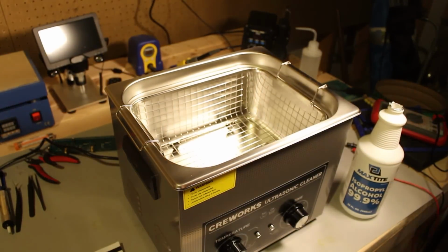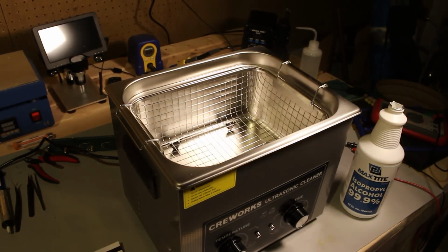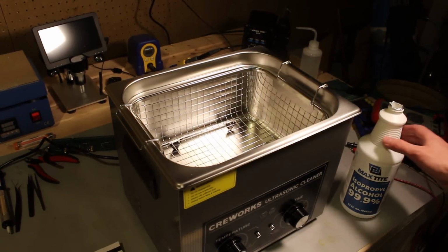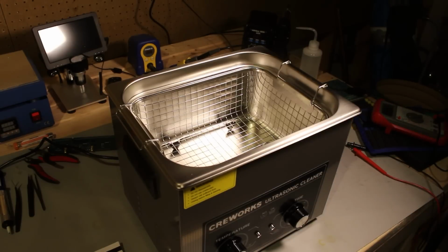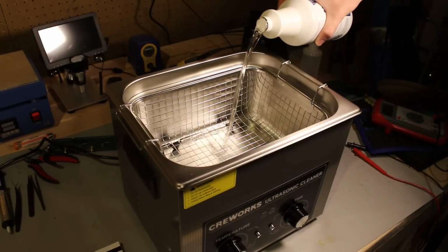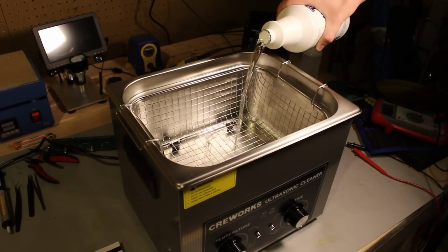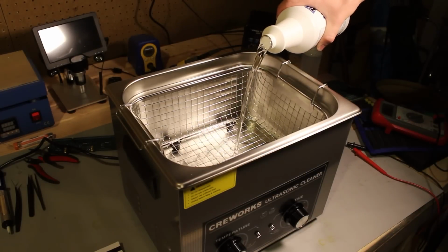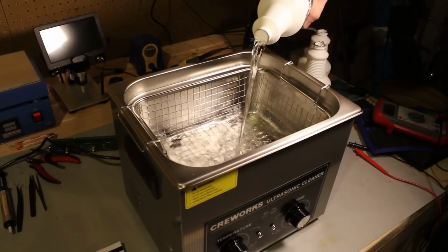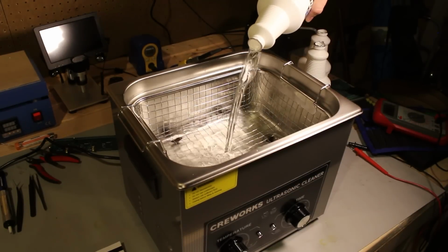You can use a brush to clean everything off, but luckily I got this cool new toy to play with. Introducing the ultrasonic bath. It works by passing high-frequency sound waves through the bath, creating tiny bubbles which then collapse and remove contaminants from the PCB. It took 3 quarts of isopropyl alcohol to fill the bath, which is quite a bit.